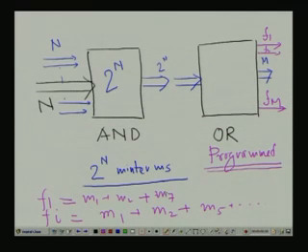So, I take these 3 minterms, and M1 plus M2 plus M7 goes to F1. Say Fi is M1 plus M2 plus M5 plus M9. So, these m outputs can be constructed from 2 to the power n minterms. This is the concept of the PROM.